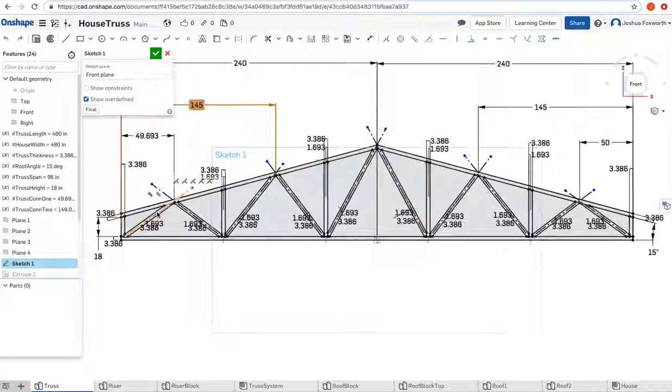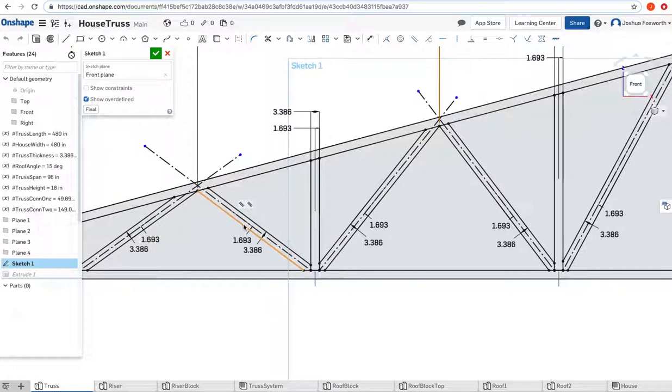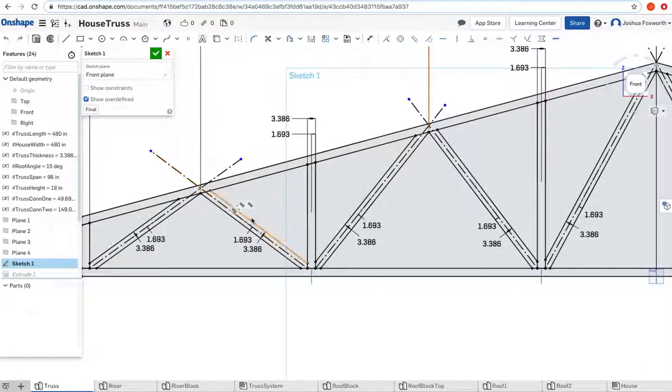We then used construction lines to create a line that runs from the midpoint of this vertical connection to the connection point there, and then defined the cross-sectional thickness here as out from either side of this middle construction line. And the thickness of the vertical ones is done the same way. There's a midline defined, and then the member is actually defined as extruding out from each side of that.